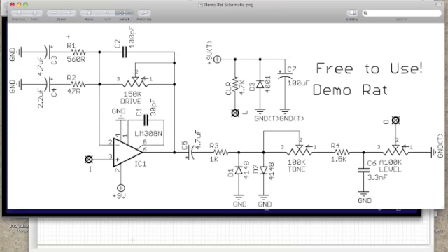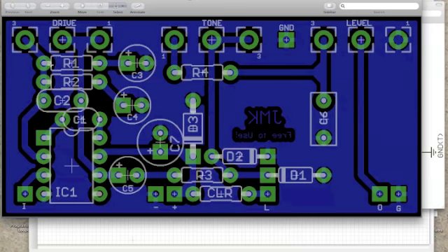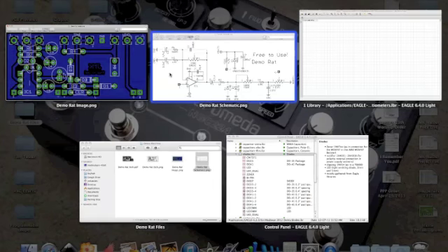R1 is the part, and the device is a resistor. Does that make sense? So we've got a resistor, which is a device. R1 is the part number. 560R is the part value. This thing right here, the little zigzaggy line, is the symbol. This sort of tubular shape corresponds with the package, which also includes the pad size and the pad hole, as well as the graphic overlay for your silk screen. So that's the differences between all of these parts.